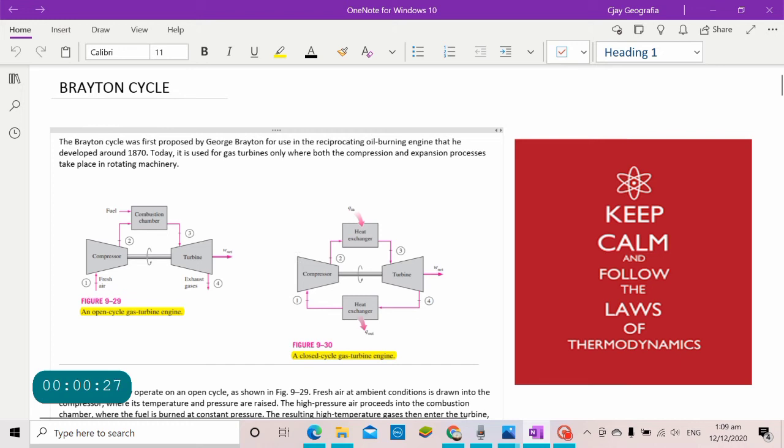gas turbine engines and air breathing jet engines also follow the Brayton cycle, although the cycle is usually run as an open system, and indeed must be run as such if internal combustion is used. It is conventionally assumed for the purposes of thermodynamic analysis that the exhaust gases are used in the intake, enabling analysis as a closed system.